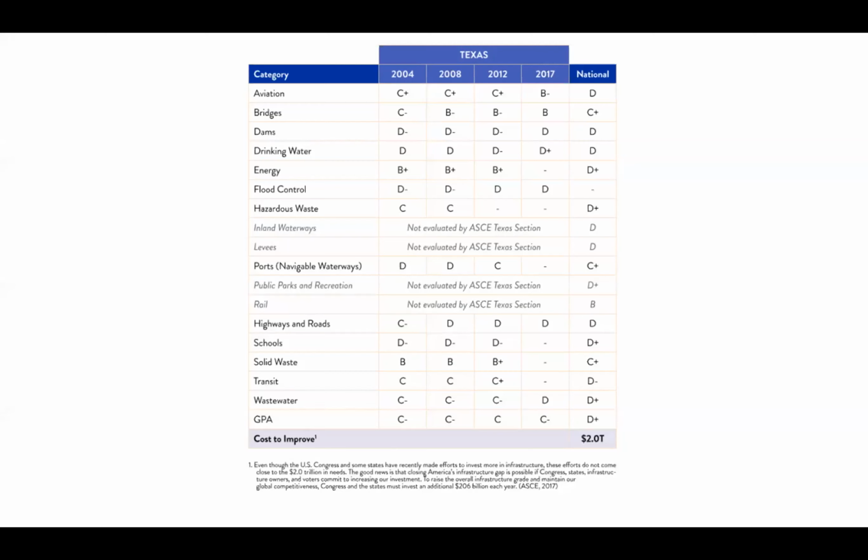As far as I know, you are restricted from flying drones over bridges. That is, if they're active roadways. They can be used on the sides and underneath. The lighting condition is not always the best for using drones, particularly if you're shaded underneath. So it still requires some human effort. But I think we're definitely going that direction. Probably more so using technology to screen first, or pre-screen if you'd like, and then having humans go in and actually look up close at things that are flagged.